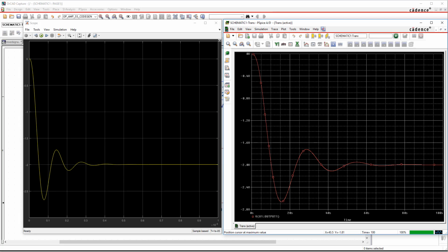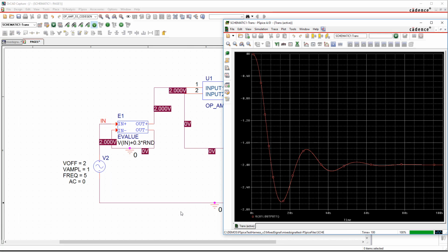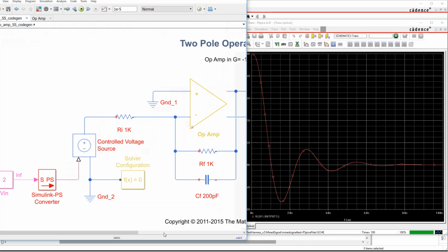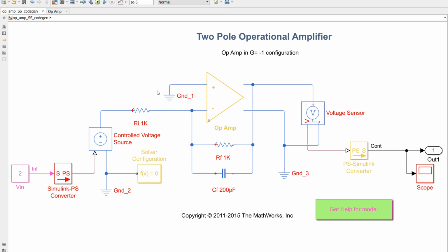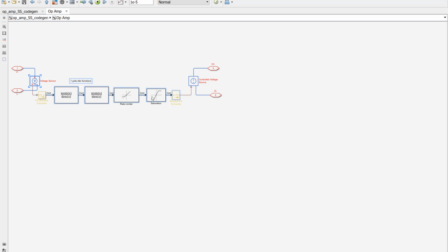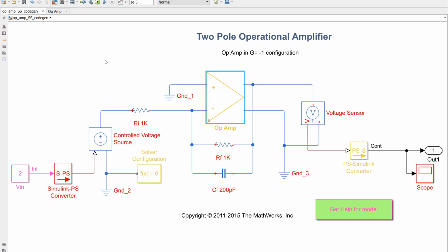There are two caveats to be aware of with this flow. The first is that any of the components that you are using in MATLAB or Simulink need to support C code generation. The vast majority of components in Simulink do support C code generation, as does the good majority of the MATLAB language. The second thing to be aware of is that when you generate code, you need to configure the code to generate at a time step